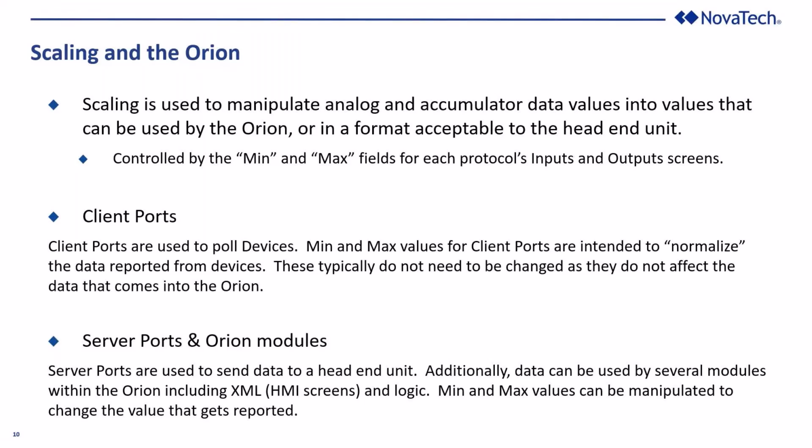One thing to note, typically you're not going to do any scaling on a client port, because when a data point comes into the Orion, the database is only storing a normalized value, or what we call a percent to full scale. It's more typical that the adjustments you make in the scaling will be on the server port heading up to your master SCADA unit.